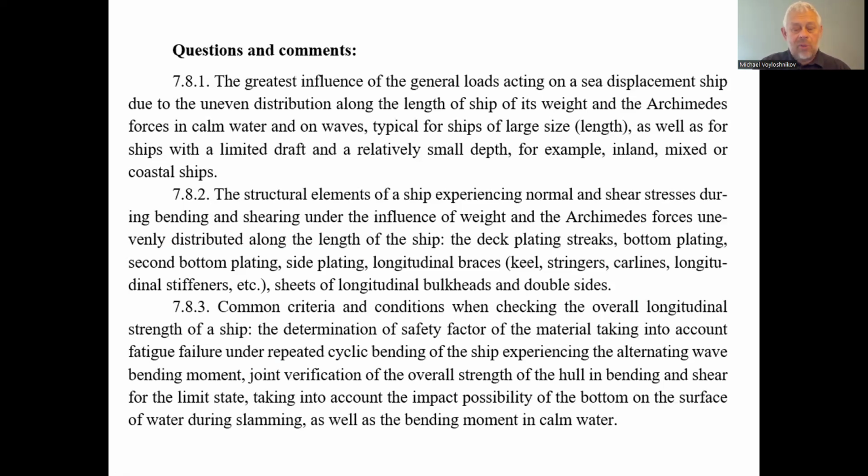Perhaps the most important is the consideration of the longitudinal structural connections of the ship hull. The longitudinal connections that are the most important, which ensure enough strength of the ship, are the decks, the bottoms, the plating of the decks, plating of the bottoms, plating of the sides, and all other longitudinal connections like keel, stringers, carlins, longitudinal stiffeners, etc.